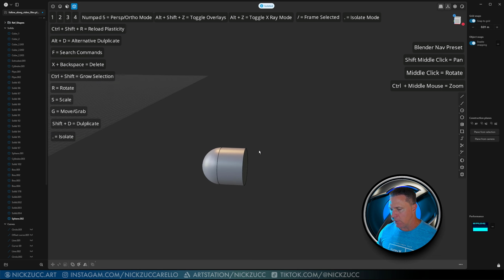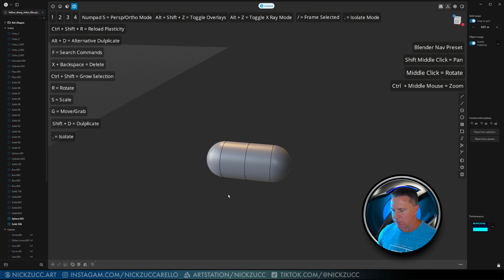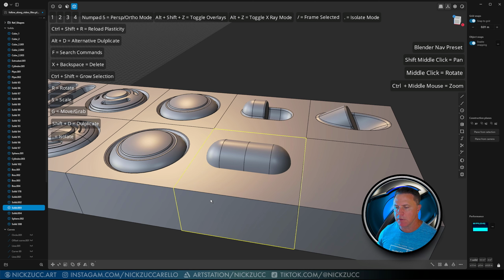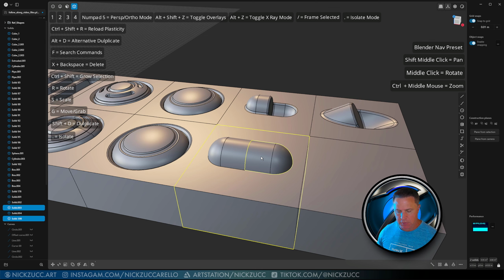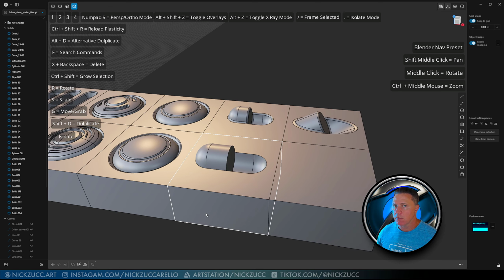So I could just do the same thing on the other side, or I could take this shape that we've got here and hit Alt X, and we can do a mirror, tap F, and then frame it right there like that, and hit OK. We're not going to merge these things together. So now we've got two different objects like this. Okay, we'll tap the period key and bring everything back, and then now we'll be able to take this shape, tap 4, and we're in object mode, and I'll hold down Shift. I'll add this one, tap Q, and then Q, and that'll Boolean those two together. Now we can select this shape, and then hold down Shift, add this shape, tap Q, and we're going to do the difference between those two. Okay, so nice and easy.